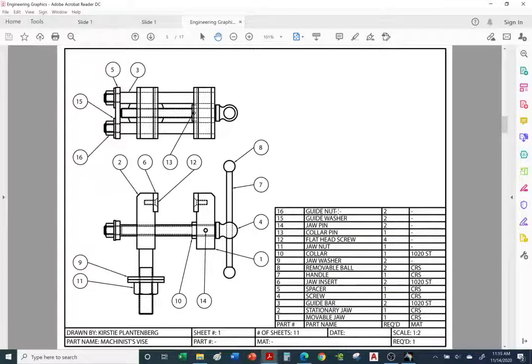Okay, here's another example of an assembly. Again, notice there are no dimensions. You can put an overall dimension just to give the assembler an idea of what size. You don't know if this is something that's 2 inches in size and height, or 2 feet, or 2 meters. So you can always put a dimension as a reference. Let's say it's 2 feet. You can put 2 feet in parentheses. Also, if you want to put an overall length, that's optional.